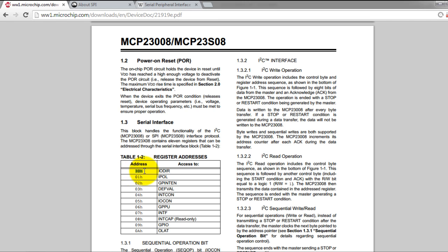This is that register's address. You have another register that sets the values of the pins. That is the address for this register. With this register, we tell the IC that we want the GPIO pins to be outputs by giving them the value of 0. We then use this register to set the outputs to either high or low.